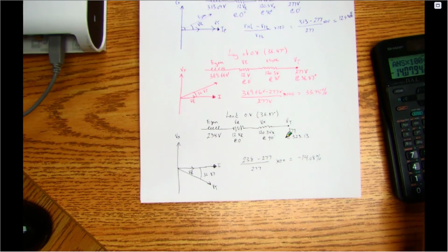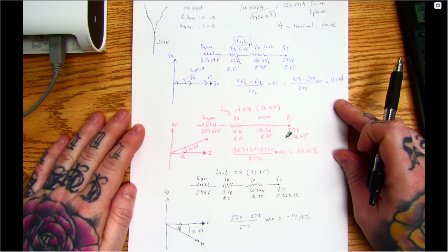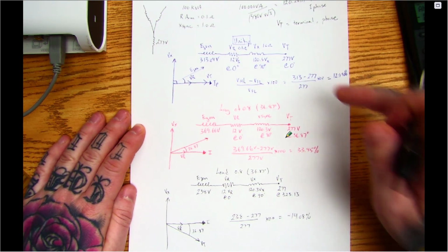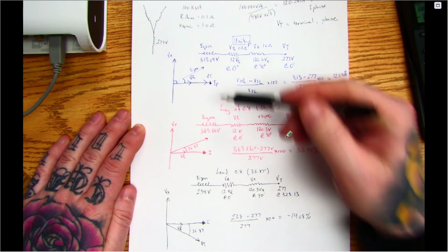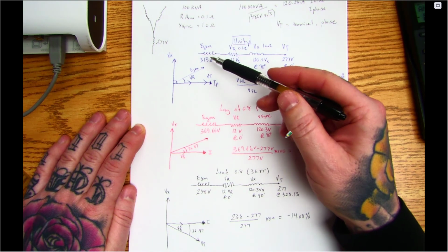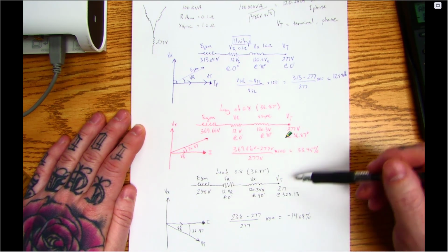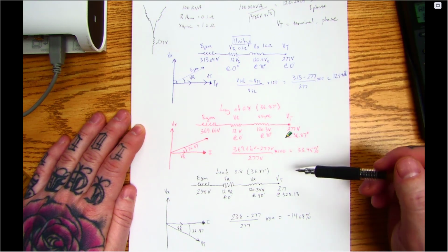We'll prove these theories, but I just wanted to get it all on one page so that we can compare. So again, unity, lagging, leading. Our E-gen, look at the difference that's happening. This is our unity. It's increasing for our lag. It's decreasing here. We're actually not going to maintain our terminal voltage in our lab.